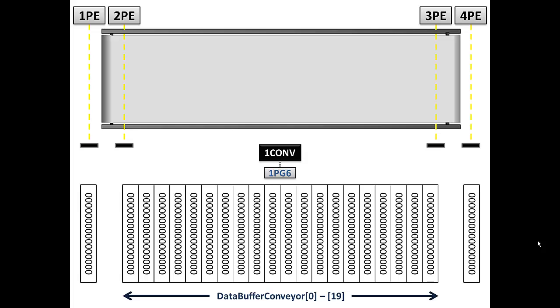When a carton hits the first photo eye, whatever barcode has been read in, we're going to put it in that first register. Then when we turn on the conveyor, it's going to start putting out pulses, and when the carton hits the second photo eye, we are going to start loading that product code into those words, and every time we get a pulse, we're going to move that to the next position.